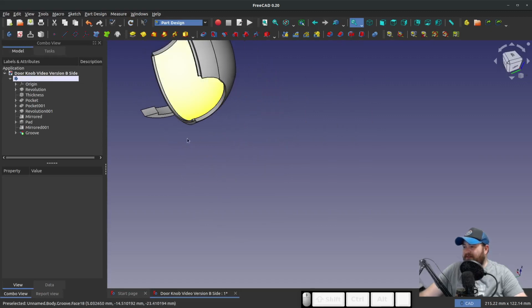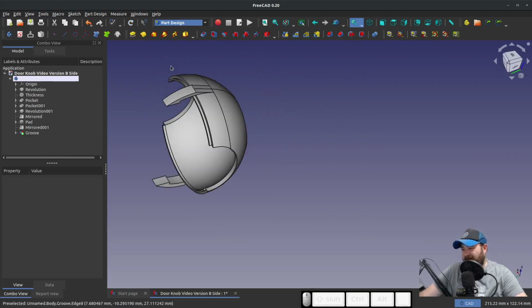So I've designed it with the snaps on the outside. And again, there's no right and wrong way to design things. It's just evaluating your needs. If you wanted to have a completely smooth face, right, it might be better to go with an annular snap and maybe add a little hole that you can put in a flat head and pry it apart if you have to or something like that.